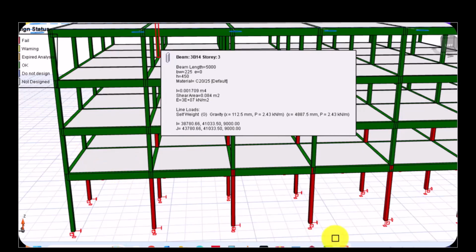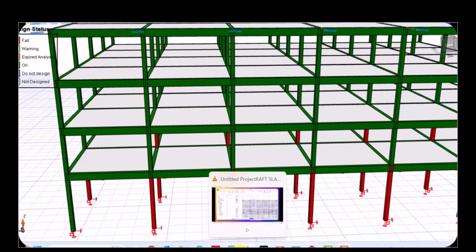For a multi-story building of 4, 5, 6 floors, by looking at it, you will surely expect failure, because you cannot just keep increasing the demand on a structure without adequately increasing the cross-sectional area. There needs to be a balance between the axial load being accumulated and the size of the column needed to carry that load.